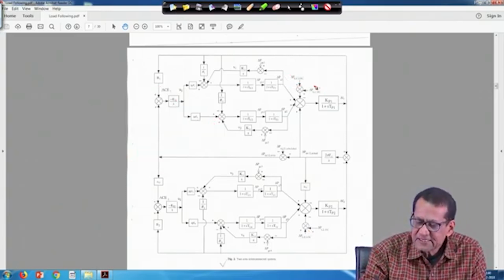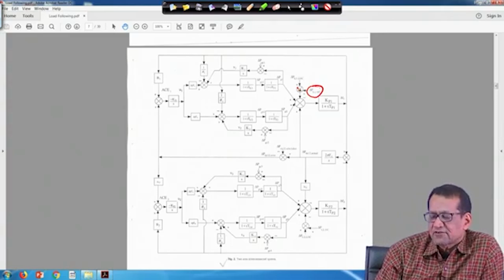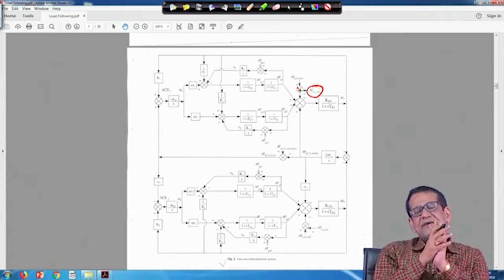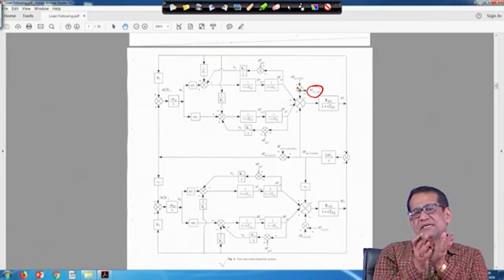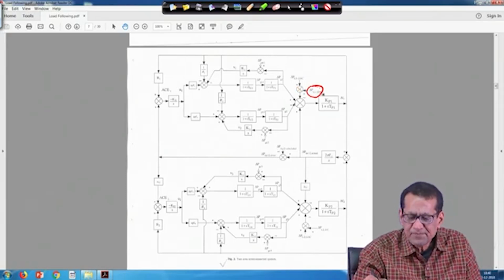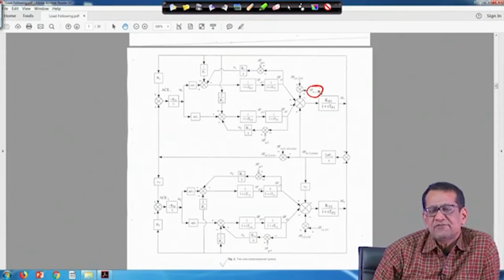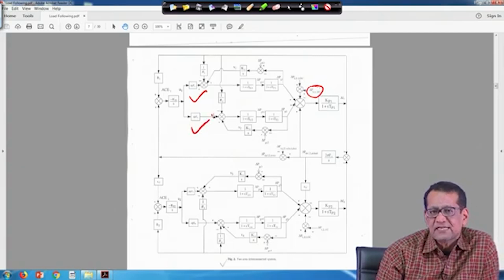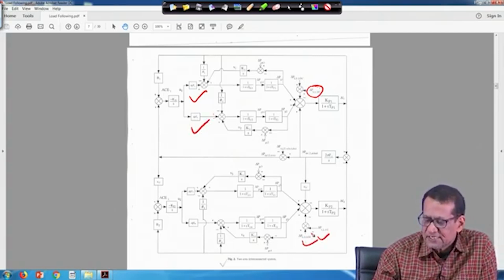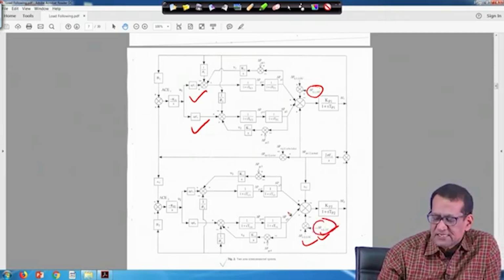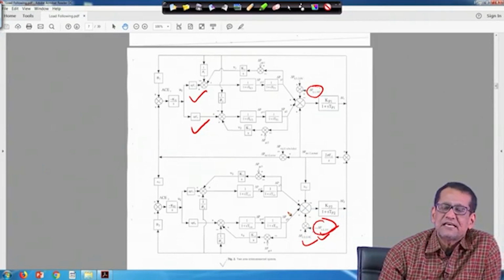then in that case, you see that is the uncontracted power demand in area 1. If apart from their contracted power demand, any excess power demand is needed by any distribution companies in area 1, that will be reflected in area 1, and it is expected that the generating units in area 1 have to supply this power, right, according to the ACE participation factor. Similarly, for area 2 also, the uncontracted power demand has to be supplied by the generating units in area 2, right.